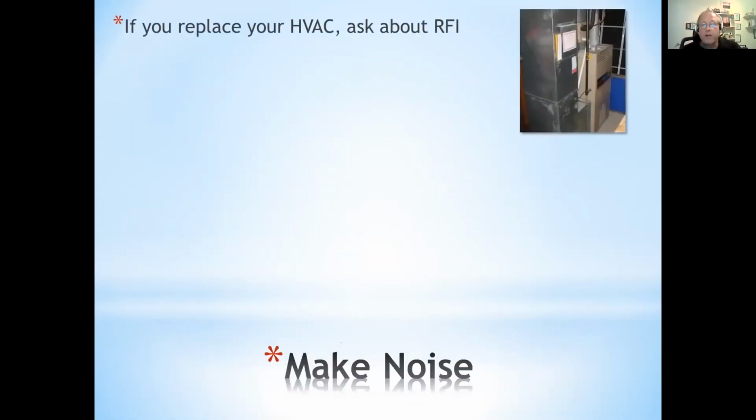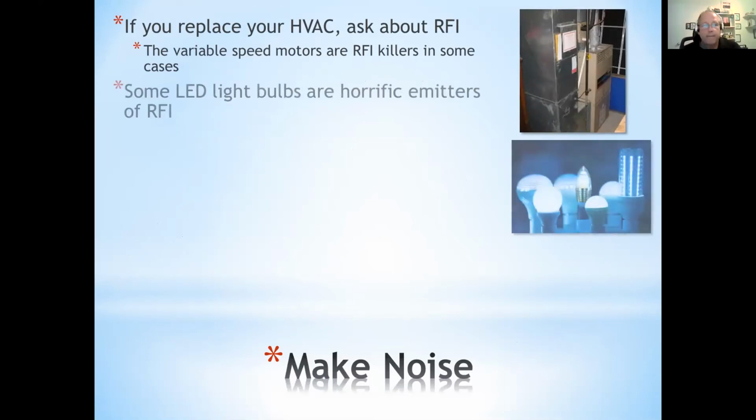If you replace your HVAC, ask them about RFI, right? A lot of these new ones use variable speed motors that are pulse width modulated motors, and they are notoriously RF noisy. Some LED bulbs are horrific emitters of RFI, and we're going to have a little demonstration of that here in a little bit.